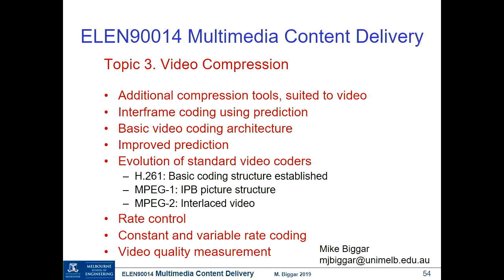For JPEG compression, my question is about the DCT. From the DCT, all we know is that it separates the high frequency signal, right? And it concentrates the low frequency in one area. So do we get rid of the high frequency from the original picture? Well, it's a choice that we make. It depends on the quantizer. But normally we find that the high frequency coefficients have a very small magnitude, and so if you remove them it makes very little difference.